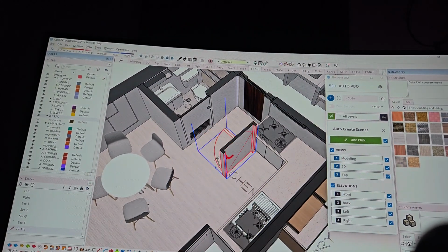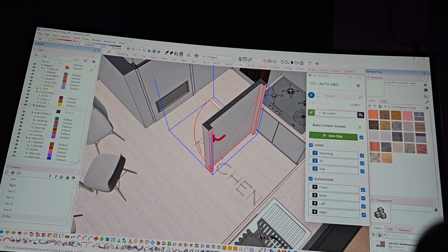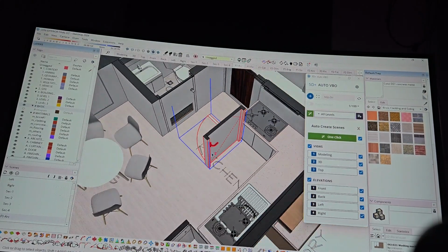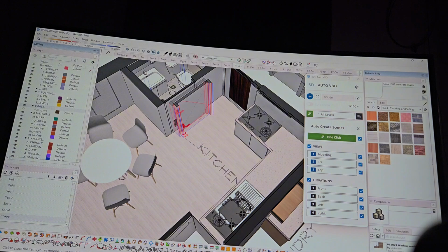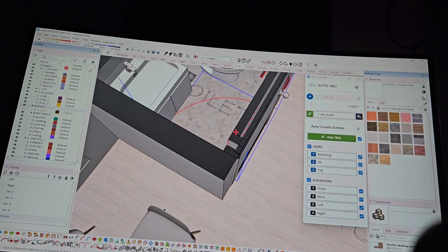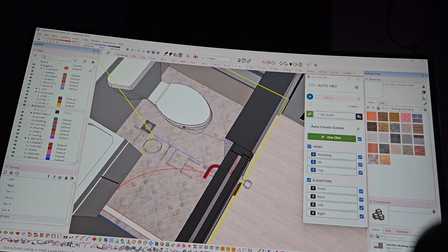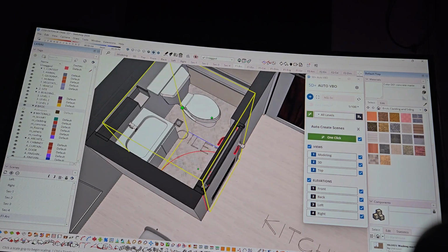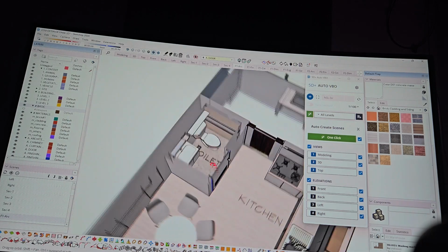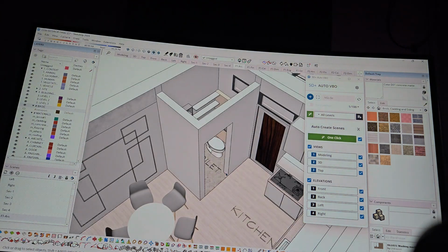And I'm using shortcut keys on my keyboard, if you can see, just like that. For our flip, I actually assigned shortcuts for that. And then we will replace it with this door. The nice thing with dynamic objects is that you can rescale it like this, and you will see that the door jamb is still the same size, does not get resized. Okay, so bye door. We have a new door here right now.